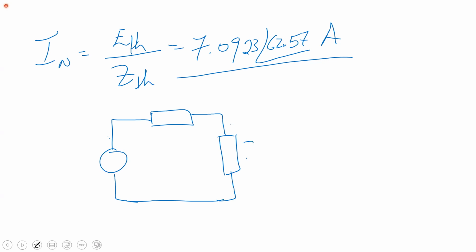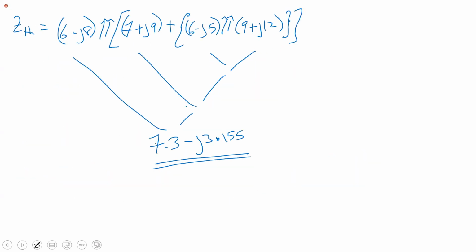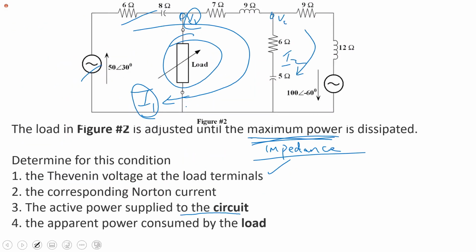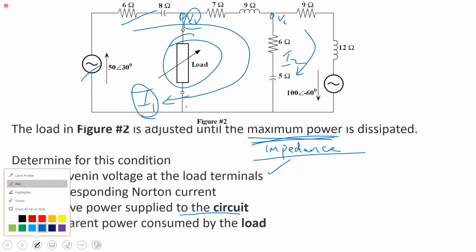Sir, I have a question to answer that. Go ahead. I can go back on the diagram. Let me show you. In the scenario that you had worked out IN first, you would have replaced the load with a short circuit, and you would have done your mesh, and you'd have found your I1, I2, I3. It's supposed to come out back to the exact thing, or the principle in itself would be correct.